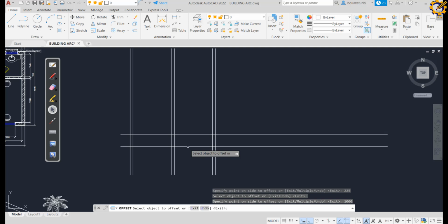The one that is common in terms of use is the strip foundation, and strip foundation is used on soil that has good bearing capacity. If the soil in your area has good bearing capacity, then it is going to be strip foundation. In most cases, strip foundation is used for building fences, wall fence, something like that.